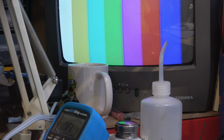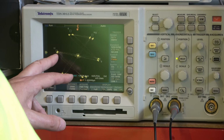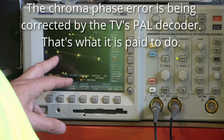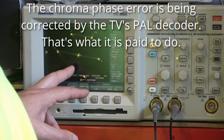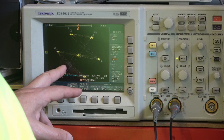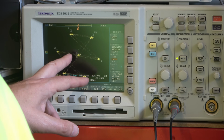And the interesting thing about that is, on the monitor, you'd be hard pushed to see any difference as I swing chroma phase backwards and forwards. Just nothing really happening. But the vectorscope is a much more sensitive measurement than just your eyes on a monitor. And I switch it back to the 0 position for chroma phase. There, I think it is.